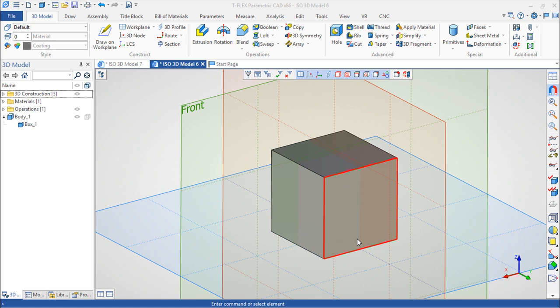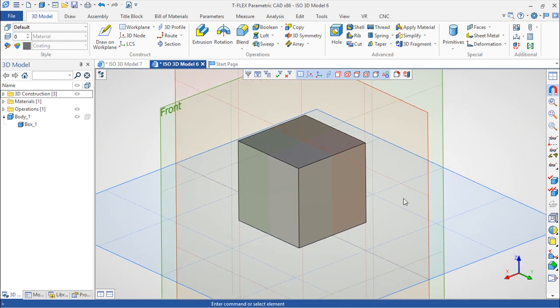So starting with the mechanical loads. These are a type of loads that are used when we are modeling studies of linear and nonlinear static analysis of structure strength. We have a lot of different types of calculations. We can include also buckling loads and cyclic loading, where we can take into account the fatigue. We'll try to see briefly the different types of loads that we can apply to our models, but